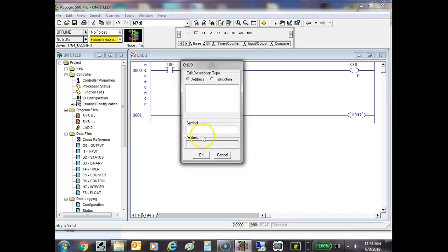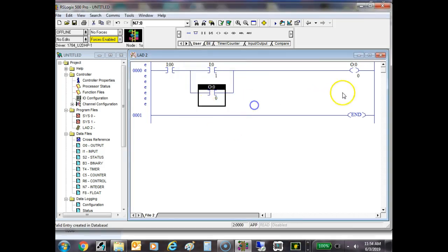What that means is if I energize this, that's what we say when we put power across a coil, even though this is not a real coil, it's a simulated coil in a program. What it does is coils control contacts. And notice I gave this contact the same address as that contact. So anytime I energize this, this contact over here is going to close also.